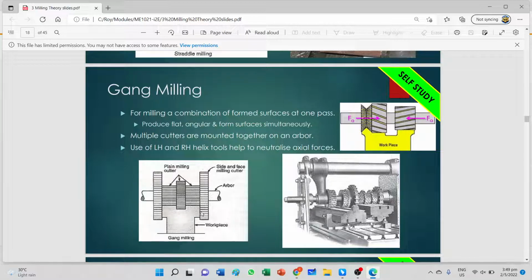So actually, horizontal milling machines are ideal for companies or shop houses that do small batch production of components. They make use of horizontal milling machines so that in one pass they can machine out a contour accurately, which reduces the setup time and the machining time.